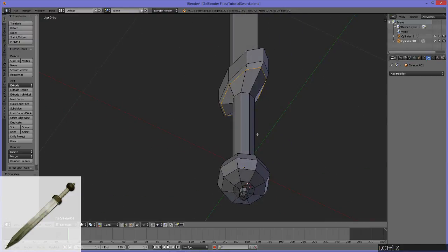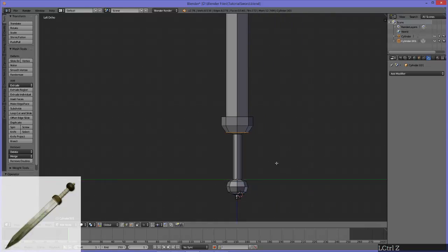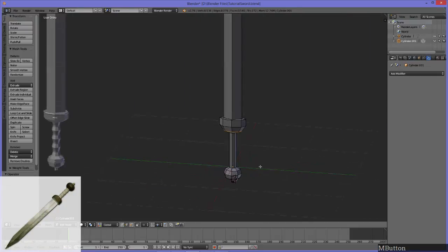Too thick, actually. So let's try GG again, go up less, and GZ. Yeah, still too high. Let's just give it a little bit and GZ it down. This will also help in rounding off. You can do GG and then GG again, and that'll really quickly round out your model. I think I like that look though, so we're gonna stay with that.